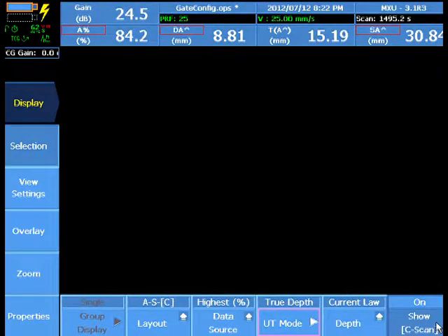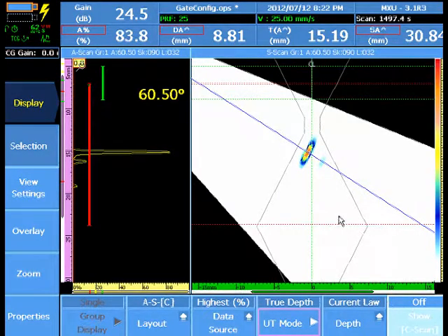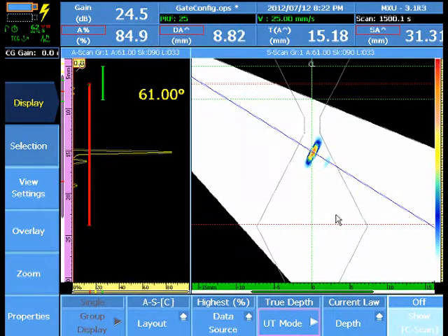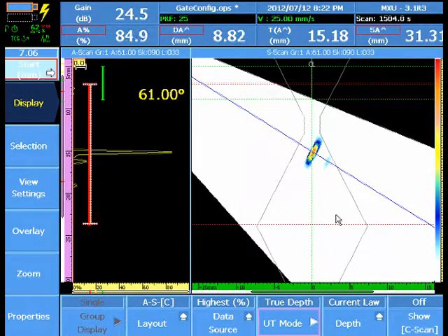On the right hand side panel, there's also a function key associated with the gate. Selecting the gate function key one time enables the gate parameters to appear in succession. As I hit the gate function key again, it will take me to start, width, and threshold of only the gates I have displayed under the overlay in the display menu.